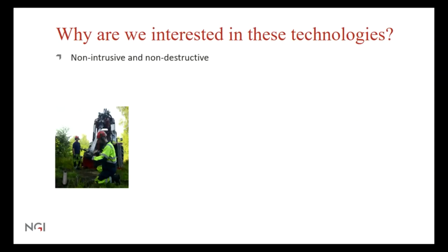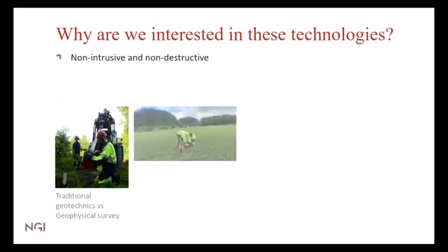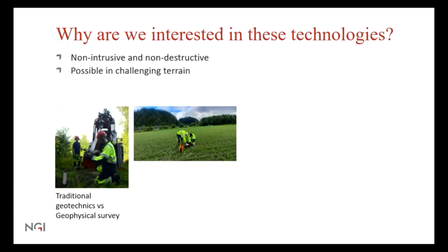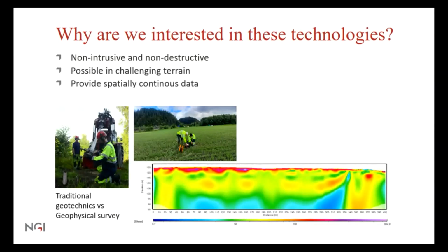And then yes, there are a lot of challenges with using traditional methods for ground investigations, and this is an image of an ERT survey in the field. I forgot to say also, drilling is very challenging, especially in urban areas, when we think about infrastructures that are underground. So you cannot just go anywhere and drill anywhere. There is a lot of investigation you have to do in advance in order to place a borehole. And so the idea of having a non-intrusive and non-destructive method to find out about the ground is extremely attractive, especially in challenging terrains. And the image shows the ERT survey done in one of our transnational accesses.